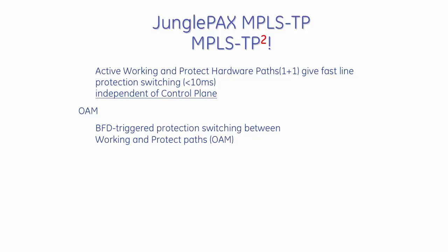As I mentioned earlier, with the default of 3 times 3.3 milliseconds, this means that you get your 9.9 milliseconds of detection. However, if you need shorter detection times, you're able to drop the number of heartbeats you're waiting for.